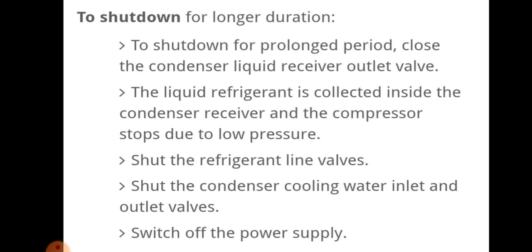To shut down for a prolonged period, we have to close the condenser liquid receiver outlet valve. Then the liquid refrigerant is collected inside the condenser receiver and the compressor stops due to low pressure.